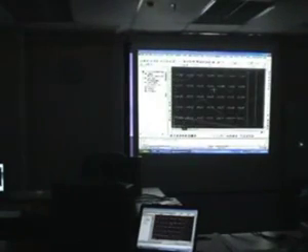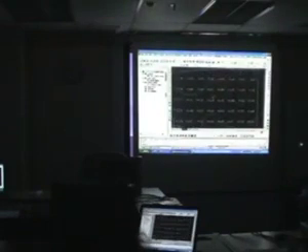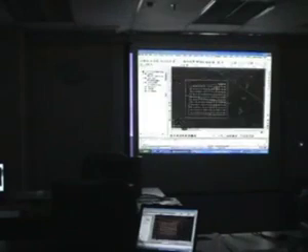So this is more for you to print a drawing like this and hand to your contractor, so at least they know how you're going to level out the existing area. So plus indicates, of course, fill, and minus indicates the cut. So that's your grid volumes.